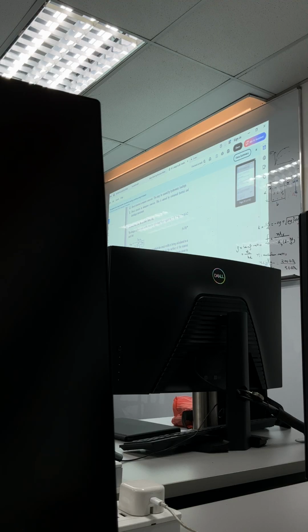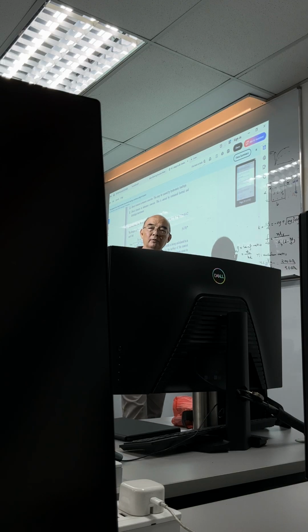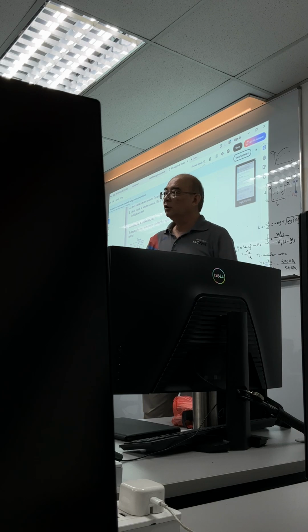Okay. Now this chapter, actually they repeat what they talk about in the early chapter, chapter 4. Okay, here is this one: lateral tension in matured concrete. The design surface crack width may be calculated from equation 6.10 in section 6.4.2, such that, okay, section 6.4.2 is in chapter 6. This is chapter 11. So in chapter 6, they already talk about the calculation of crack width.